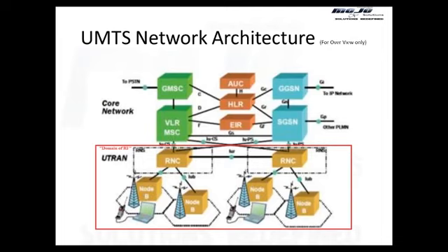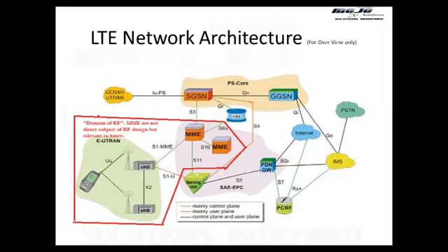The basic difference between the two technologies, UMTS and LTE, is their air interface. UMTS used the air interface WCDMA, and LTE used the air interface OFDMA. These are two totally different air interface technologies, which makes the spectral efficiency of the two technologies entirely different. Note down this word as well: spectral efficiency. And the reason companies are going from UMTS to LTE is basically the higher spectral efficiency.